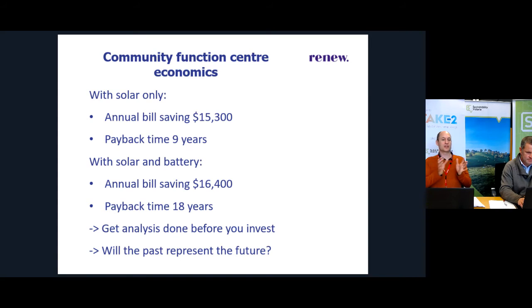Make sure you consider the solar without battery as well as the solar with battery case. So you can ask for quotes from the solar installer for both cases, so you can clearly see how much additional upfront cost that battery is costing you. And another point is, when you're doing an analysis, you're generally looking at historical meter data over the last year, for example. But be mindful if your future electricity consumption is going to change. Are you going to expand your operations? Are you going to maybe have electric vehicle charging in the future? These are the sorts of things to consider as well.